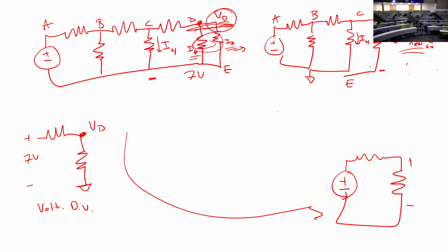I feel like there are some circuits where I try to use a lot of source transform, where there's no resistor in series with the voltage source, or even if I turn it into Norton, it wouldn't be in parallel. Yeah, that probably means you need to do some combining over here before changing your source back and forth.